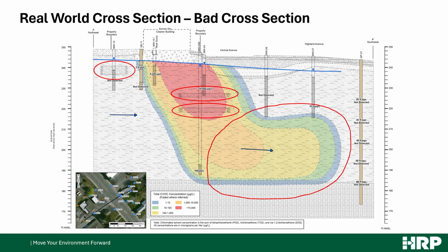We have to be thinking about the geologic setting, how the sediments that are there got there, as we're doing these boring logs so that we do have things that make sense and are reflective of the real world conditions as we are moving forward on these projects. I'll get off my soapbox now and let Chris go.